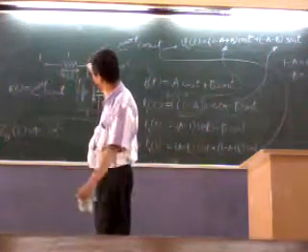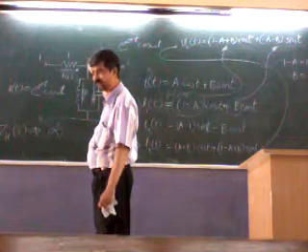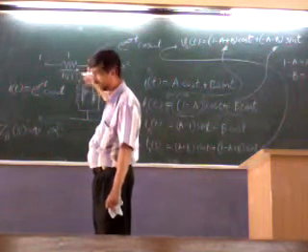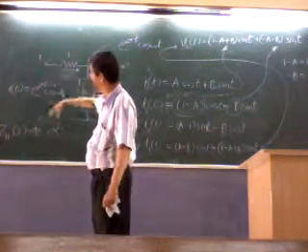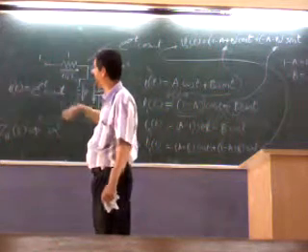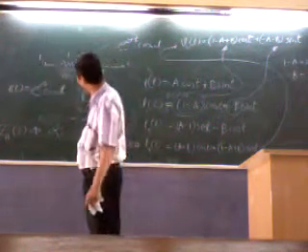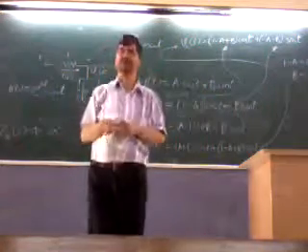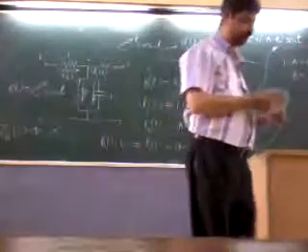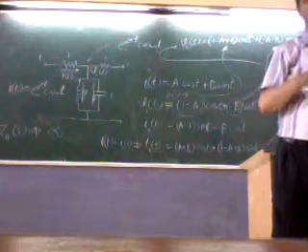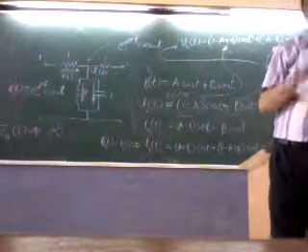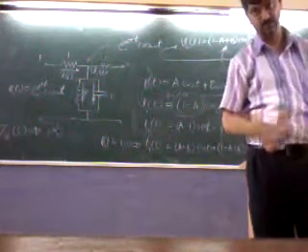For that voltage you compute the currents and find out the value of sigma and omega for which this voltage plus this voltage will become 0. These are the poles of the admittance function or zeros of the impedance function.